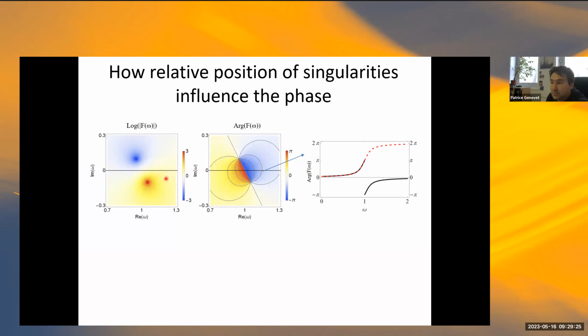And this is very interesting, because if you are in the regime for which they are separated, you see now the signal with real frequency excitation. If you send your plane wave varying the frequencies and look at the phase here, you see you have now a discontinuity, which when you sum up, you get 2 pi phase, right? And this is very important because if you want to design a photonic system for wavefront engineering, you have to be able to engineer the phase over 0 to 2 pi.